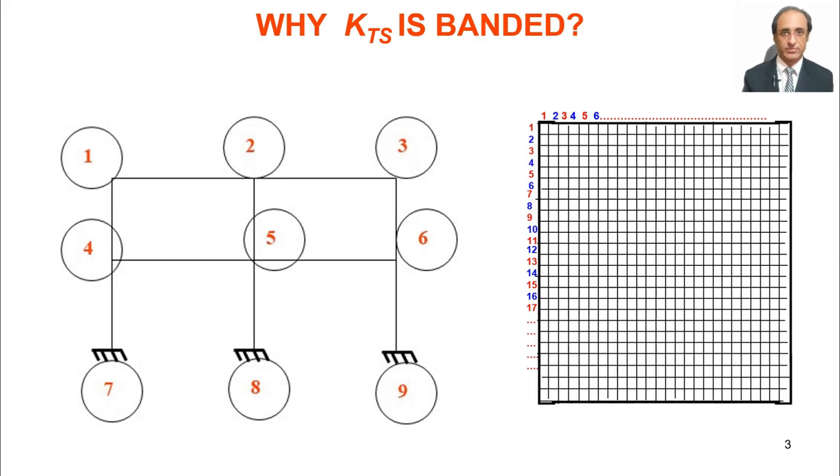So what should we do? If by first principles, by the matrix stiffness approach, means manual method, we want to find a particular column. What is the procedure? We apply unit deflection along that particular degree of freedom and find out what are the forces generated along various other degrees of freedom. They will be the particular column.